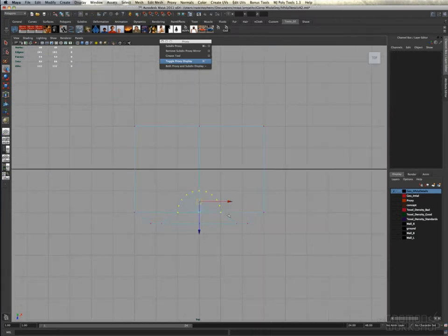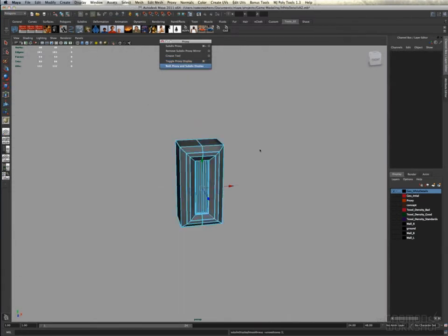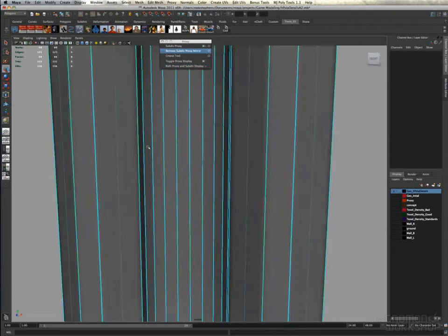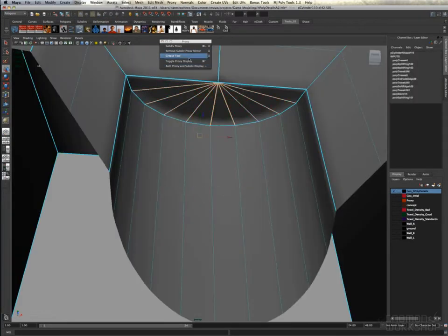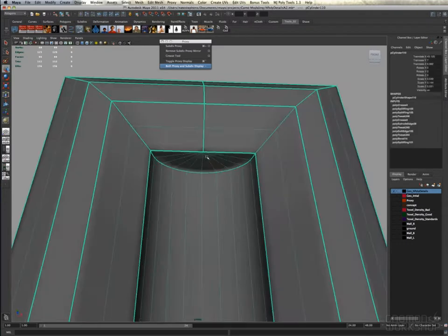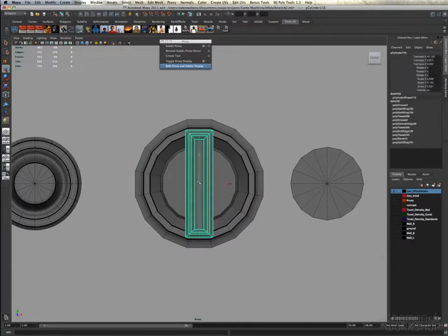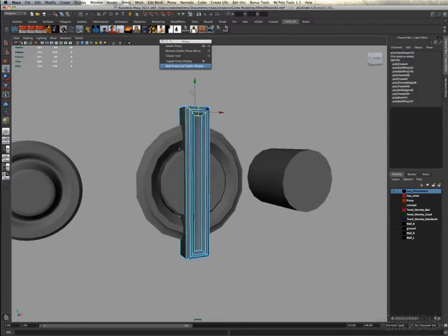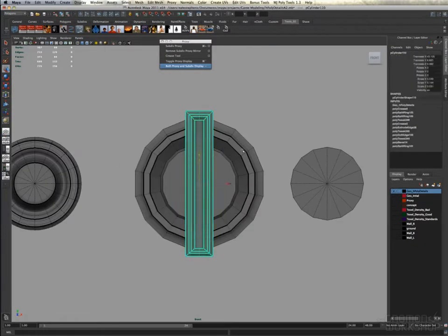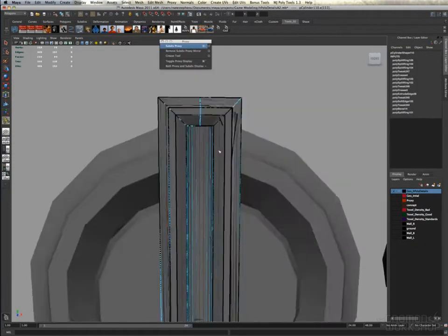So you would be correct in calling this a texturing task, actually. But since we have to do this modeling to create the texturing, I'm including it on this DVD. And so, in short, the reason why I'm doing this is just to create a high-res page of normal map details that I can place on my geometry later on instead of having to do it through using polygons.